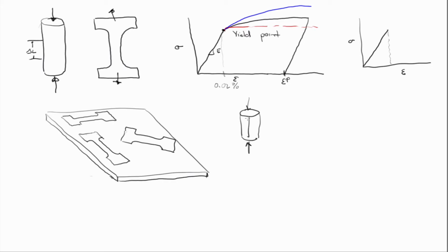However, if I apply a confining pressure to it, right? So if I confine it, the way we do these in the laboratory is the sample itself is placed inside some type of confining fluid, hydraulic fluid, and so that hydraulic fluid is then taken up to very high pressures, and then it's mechanically loaded from the ends, okay? These are called hydrostatic compression tests.